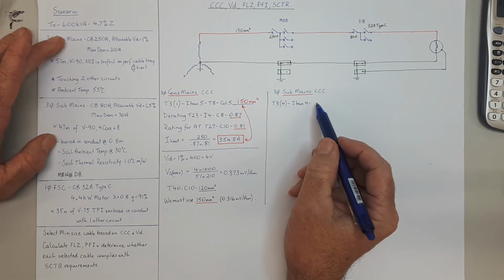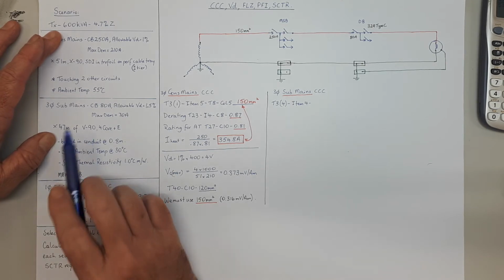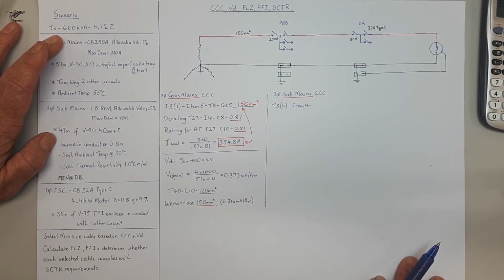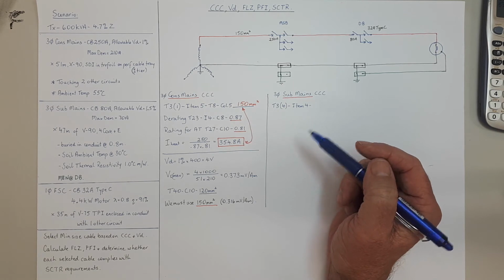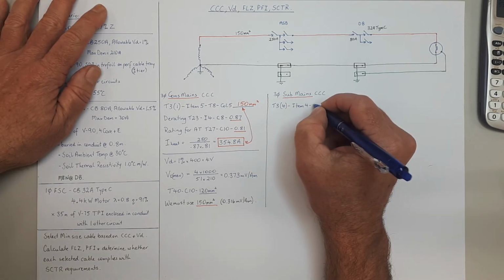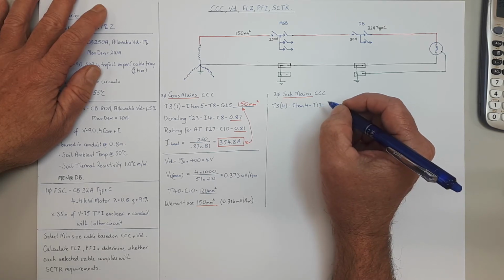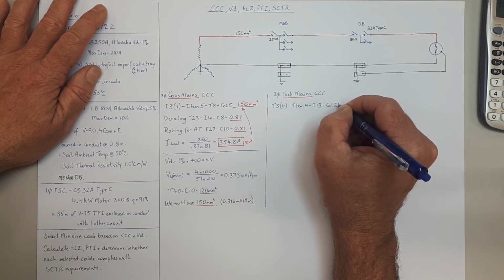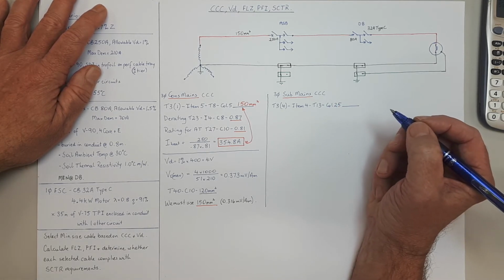Now in this case we pick 13 because this is V90, which means it's a 75-degree cable. If you remember that from your lessons, a V90, it counts as a 75-degree cable. So we pick table 13, and it's going to be column 25. That's where our cable size is coming from.